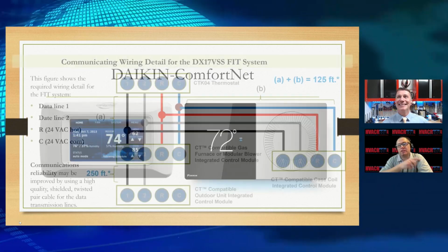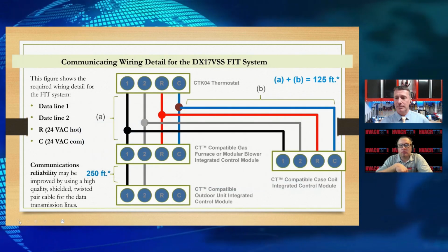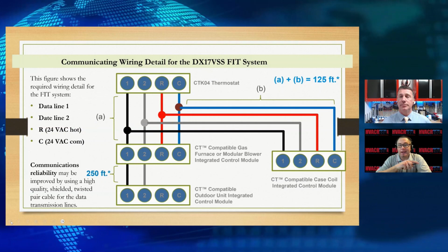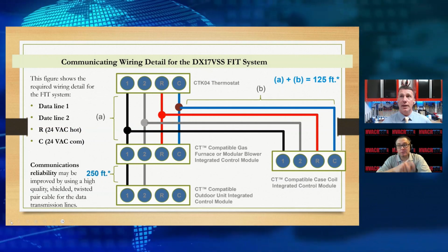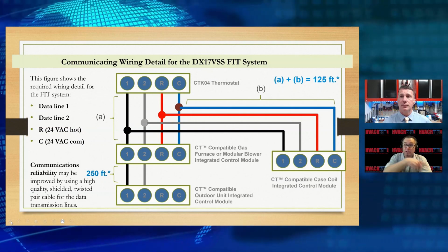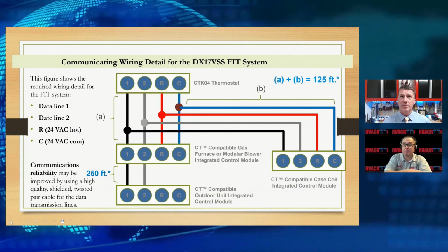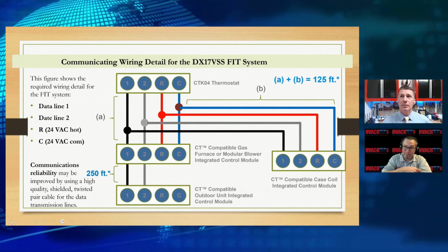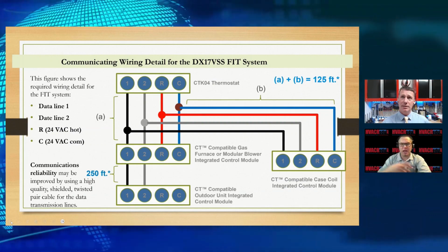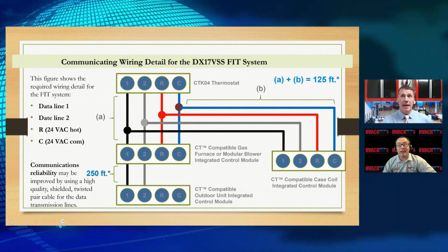Yeah, you made mention that we get that transformer of 24 volts from our indoor unit. Do keep in mind this is unitary, usually a split system. Now, when we do go and talk about a typical ductless split system, then it's coming from the outdoor unit. Where our board is, just keep that in mind. Everyone's going, "Hey, time out! That comes from the outdoor unit." Exactly, in a ductless system.